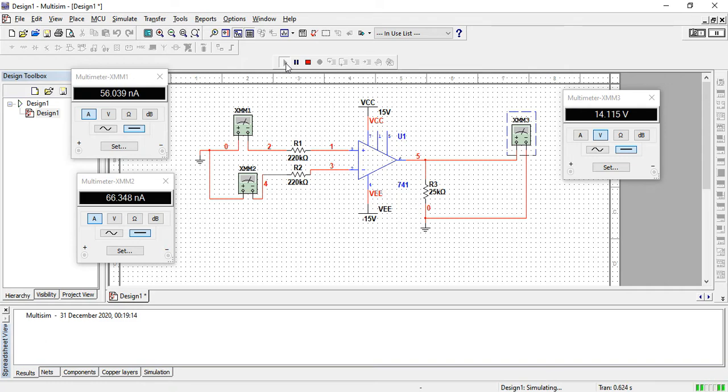Now this voltage is actually, there are still minor currents, you have grounded it, okay, and IB1 and IB2 exist, and as we discussed in the theory, if you have minor currents here, the offset voltage exists, then it is amplified, okay. The op amp picks up those minor voltages and amplifies them, and on the output again you are receiving a voltage of approximately 4.115 volts, which is very high, right?